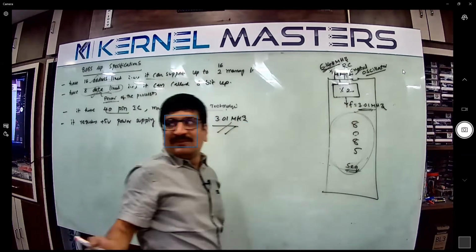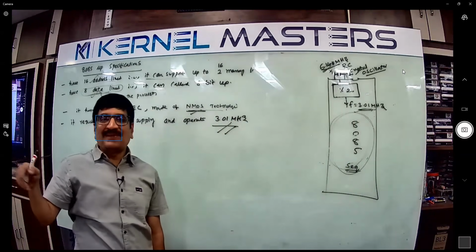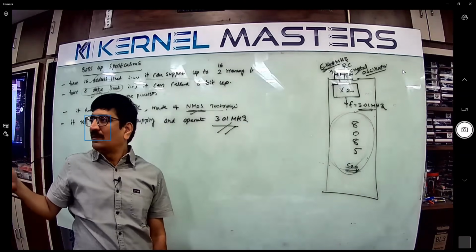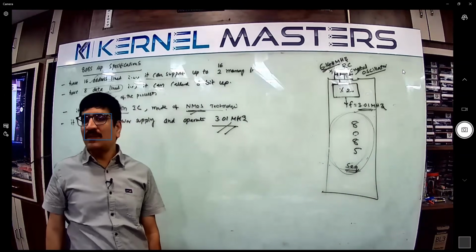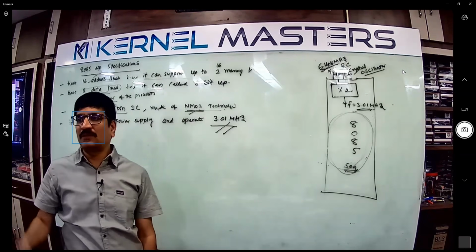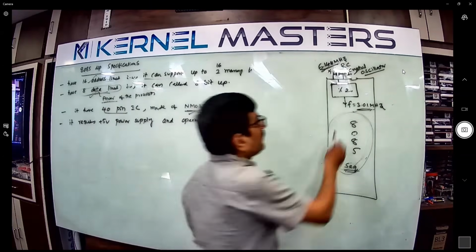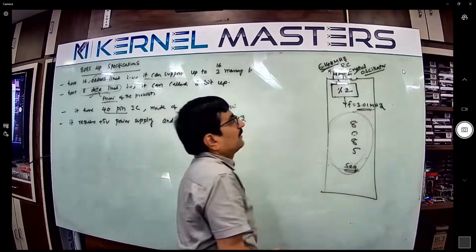You should know the T flip-flop. The T flip-flop output is equivalent to half of the input frequency, so it is a clock divider. You studied the T flip-flop in digital circuits. Counters can also be useful, since counters are also frequency division circuits.